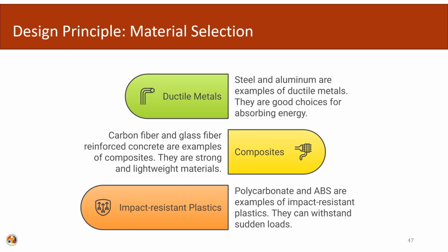After that comes the material selection part. Ductile material has to be selected. The most commonly used ductile materials are steel and aluminum, which are used in the automotive sector, in the aerospace sector, and also as sacrificial elements wherever we are dealing with protection, from bunkers to protection in buildings. So, they serve as a sacrificial sheet and the inside structure remains unhindered.